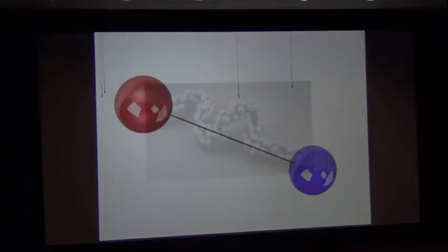What is relevant about the macromolecule is that it is longer than it is wide. And if I take one sphere, that is not sufficient, because a sphere is not longer than it is wide. But two spheres held apart rigidly at a fixed distance, we call that a dumbbell. That thing is longer than it is wide. It has length and it has width, and that can teach me about where viscoelasticity comes from and where the higher harmonics come from. Now you say, wait a minute, that thing can't really entangle with other molecules.